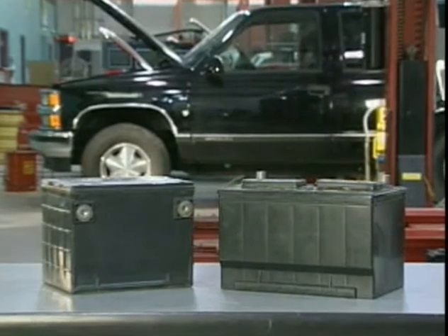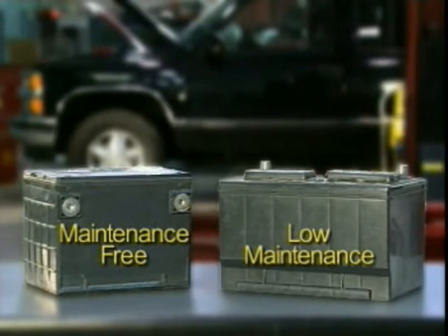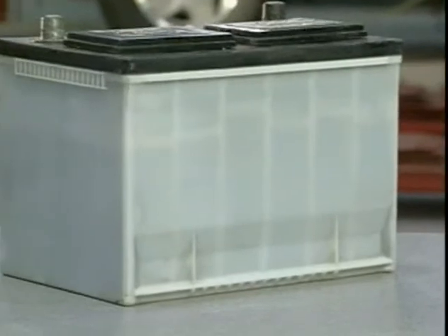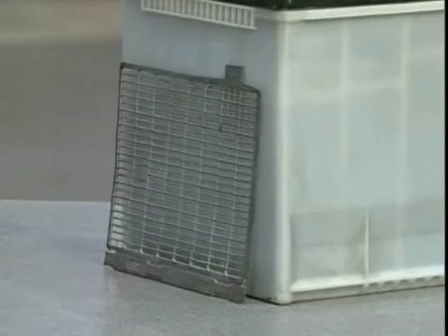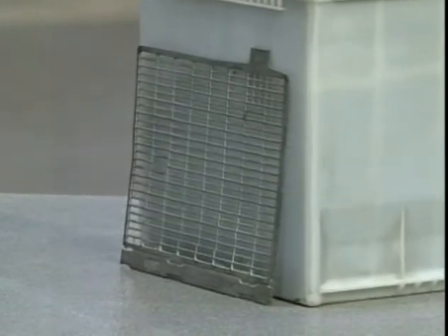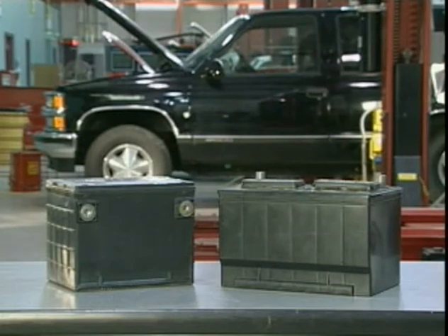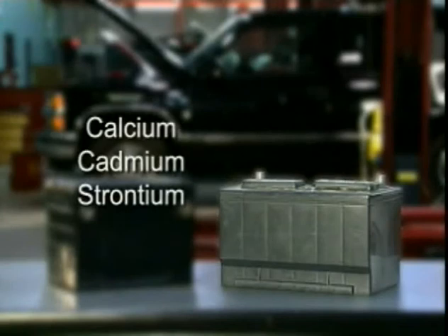Batteries you're likely to see on vehicles today are either of a maintenance-free or low-maintenance design. These battery designs have evolved from conventional batteries that required technicians to occasionally add water. The most basic part of the battery is the grid. The grids are flat metallic lattices that hold the plate material and conduct current. In a conventional battery, the grids are made of a combination of lead and antimony. In maintenance-free or low-maintenance designs, the antimony is reduced or eliminated and replaced by calcium, cadmium, or strontium.